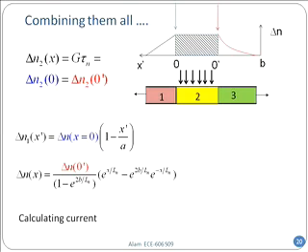So that's one side. The other side is full of traps, and therefore it is disappearing faster, and therefore before getting to the contact. By the way, where are those electrons going? They are recombining with the holes, and the holes are being pumped through the contacts. So in fact, in the green region, holes will flow in to support the recombination of the electrons. As every electron is moving in, holes will flow in, and therefore the current will flow. Because in the circuit, whatever electron gets out from one side, that must be balanced by the whole current from the other side.